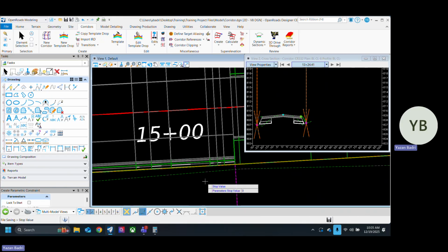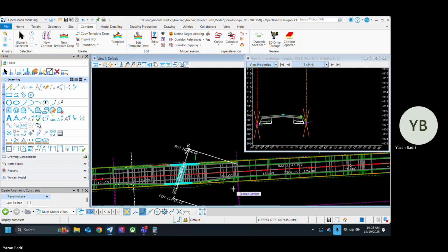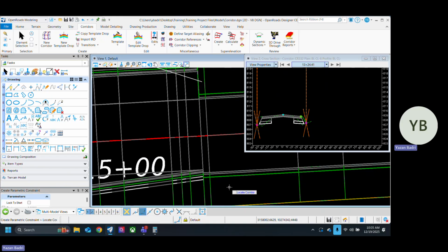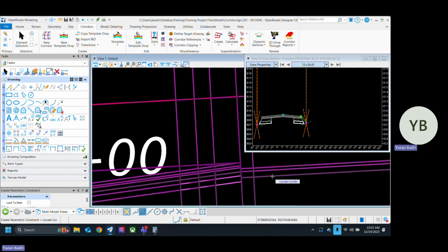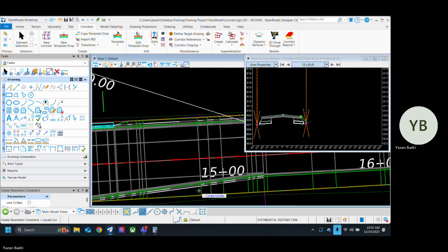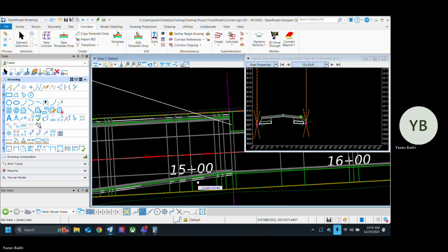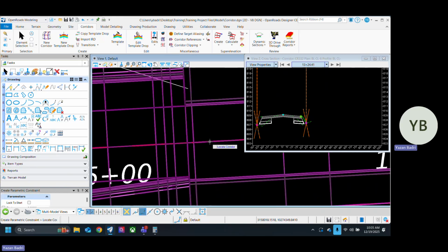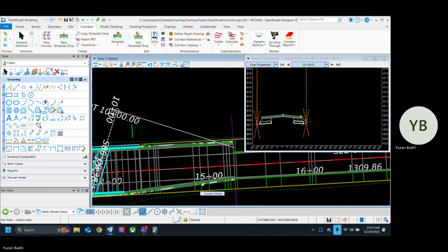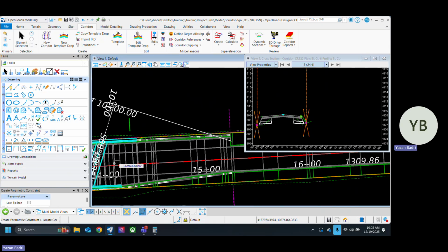It's gonna be the opposite. It'll look like this. We'll figure out why there's a small difference here. Oh, I know why. Because we did 12-foot lanes here and we did 11 here. So I'll have to come back and fix that.